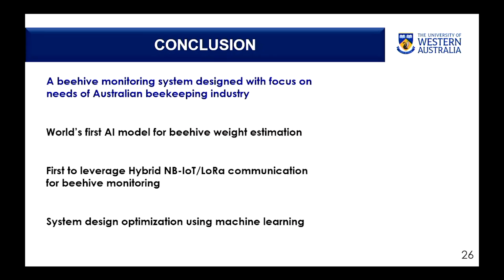I mean, it's a simple binary string that comes in. With LoRa, LoRa transmits a packet which is a string of numbers. That gets stored into the SD card of the NB-IoT system. When NB-IoT wakes up, it reads one string at a time and just transmits it. It is simply picking up the data and transmitting it because it is already in a format which my system understands.